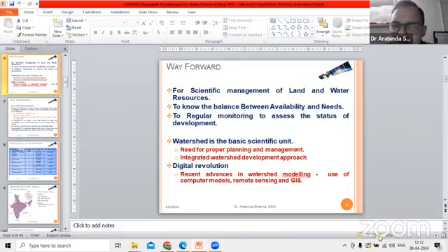Otherwise, I have to take a sample of that soil and bring it to the laboratory, where I can find the soil moisture content gravimetrically. I measure the weight of the fresh soil sample, then put it in an oven for a particular time to make it completely dry, and again weigh the soil. Whatever the difference in weight is, that gives the soil moisture. But that technique is very tedious, hard work, and may not be accurate,